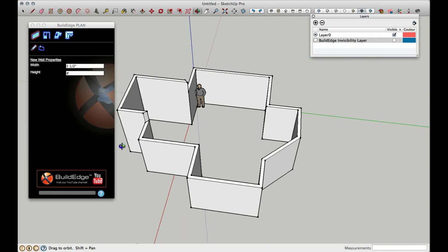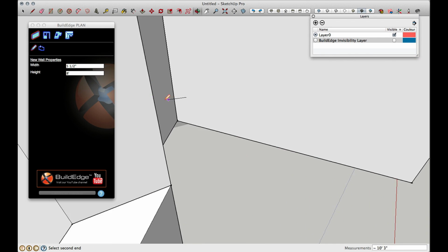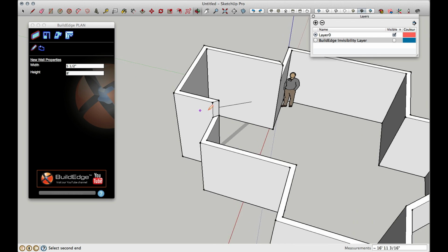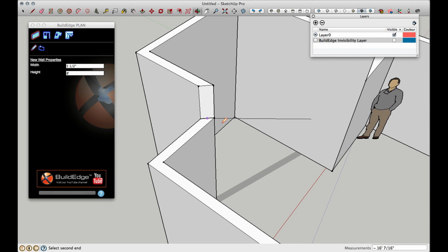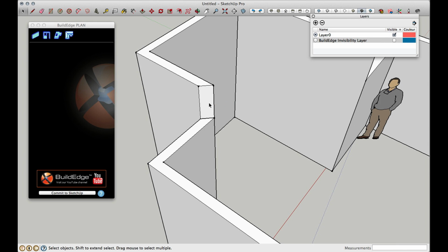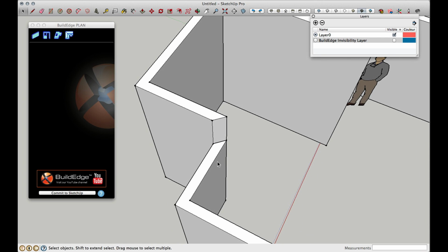Now something I do want to point out, I talked about hiding the miter lines. We don't do it on tall walls, on walls that intersect like this. That's intentional because I wouldn't have a face here if I hid that. I'd actually have this open space right here. So if walls are different sizes, we do still draw that surface.